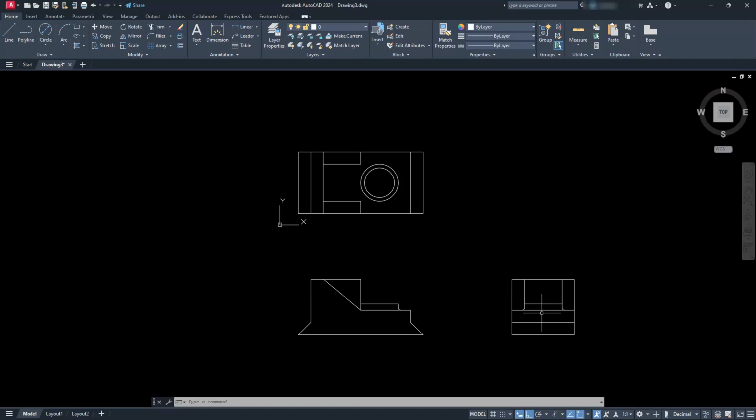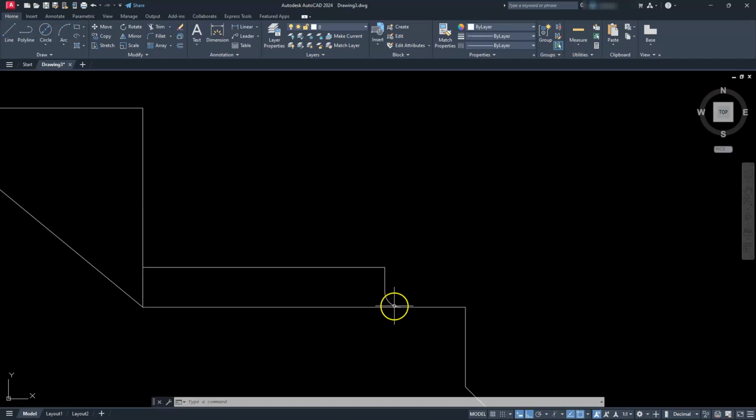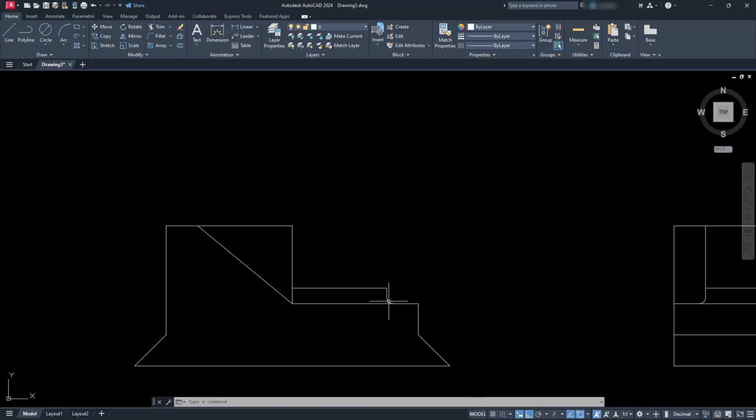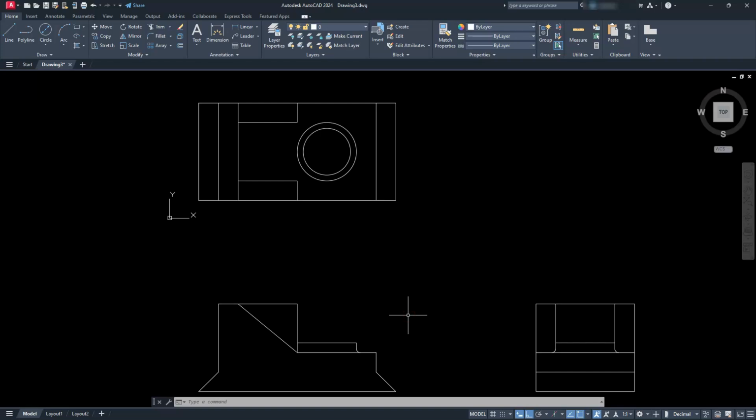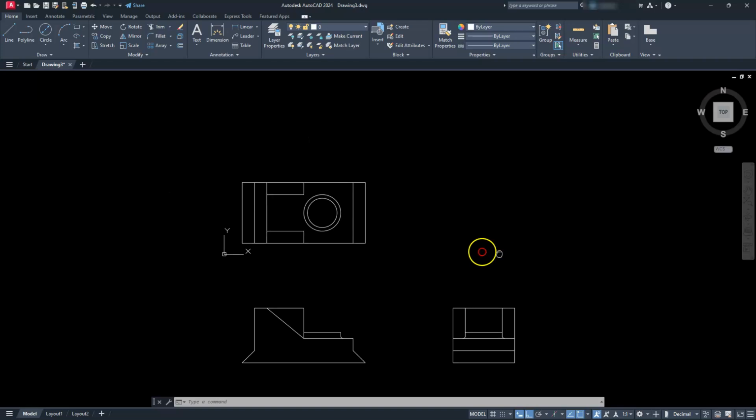I will give you a caution here, is that when you're creating a 2D isometric, doing it the manual way, one of the hardest things to do is to put these radii onto your isometric drawing. So what I tend to do, and remember that isometrics are nothing more than a picture, I'm going to go ahead and leave it off as if it's not on there. Typically that's going to either be something that's welded or something along that line. But remember that isometrics is nothing more than just giving it a pretty picture. All right, so let's start working on the isometric.